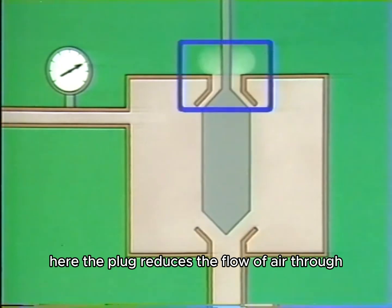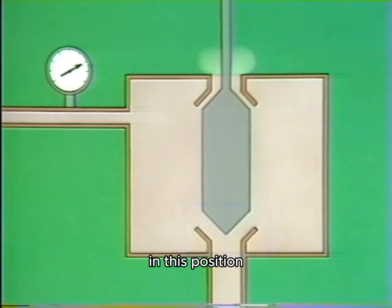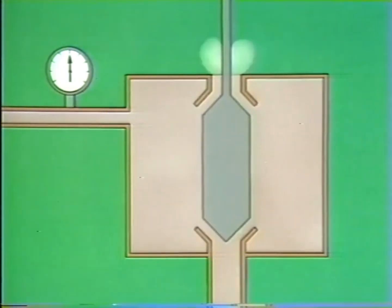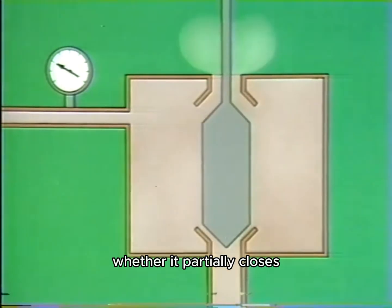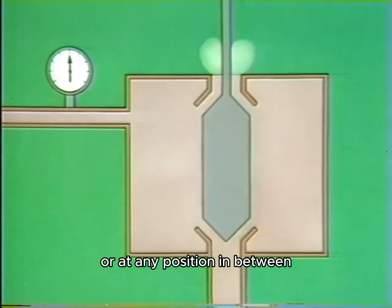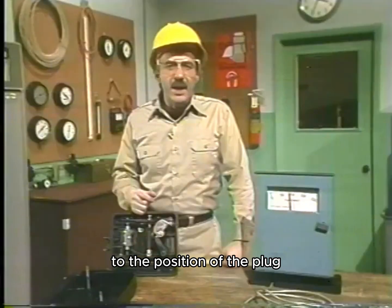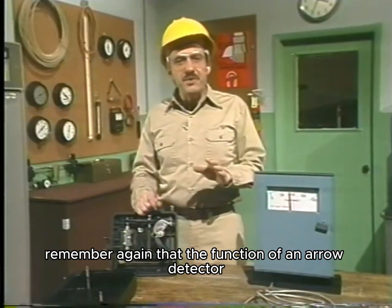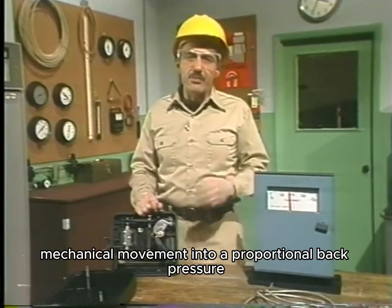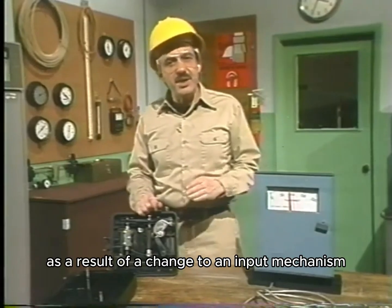Here, the plug reduces the flow of air through the exhaust port and opens the supply port. In this position, back pressure and output pressure builds. Each time the plug is positioned, whether it partially closes or opens the exhaust and supply ports, or at any position in between, it results in a back pressure that is nearly proportional to the position of the plug. Remember again that the function of an error detector is to convert a small mechanical movement into a proportional back pressure, and that each time a valve plug is repositioned, it is moved as a result of a change to an input mechanism.